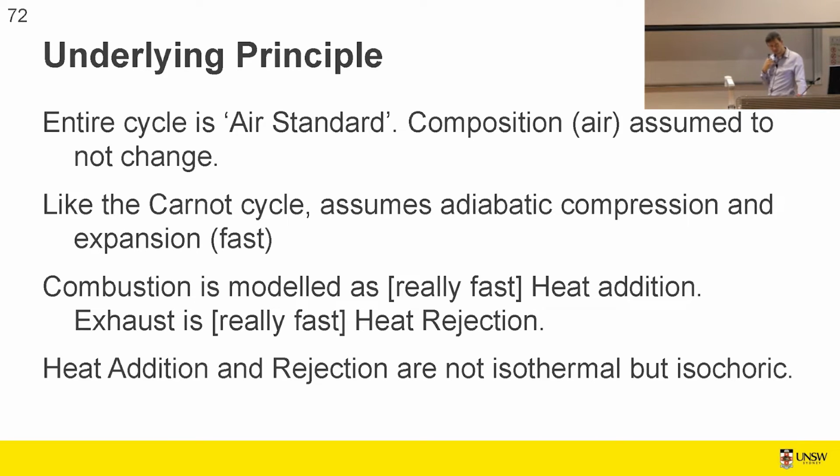But we will say, for our purposes, that this cycle is the air standard cycle. So we assume you get atmospheric air in, dry air, no humidity. We assume you get atmospheric air in at the intake, and you exhaust atmospheric air out the exhaust. That's not true, but it's close enough for our purposes. If you want to go into advanced analysis, you need to take into account the change of molecules and so forth, and you can do that in your assignment if you care to. You can do the stoichiometrics and so forth. So we say that the composition doesn't change.